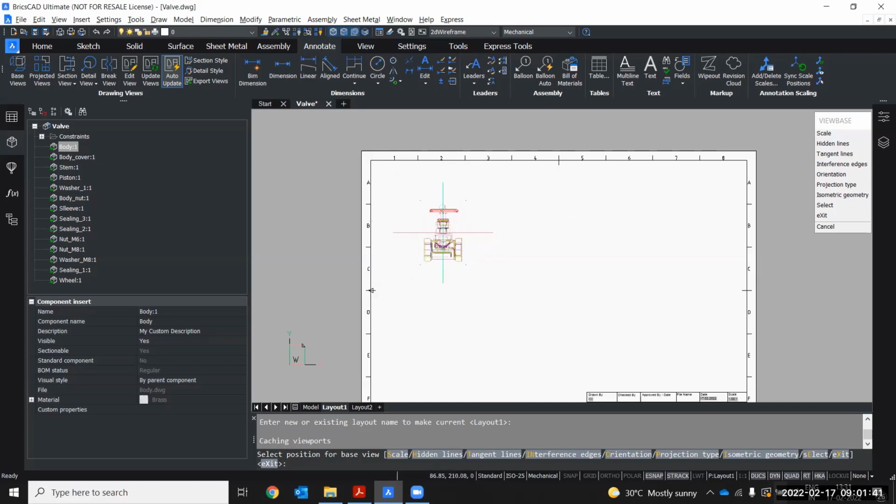Now the layout properties is something that you can predefine inside the layout settings. So the page sizes, the prints, the type of borders that you want to see, the margins, the title blocks, etc. is something that you can predefine inside your layouts and then save as a template. That is something we are not going to cover in this particular exercise.